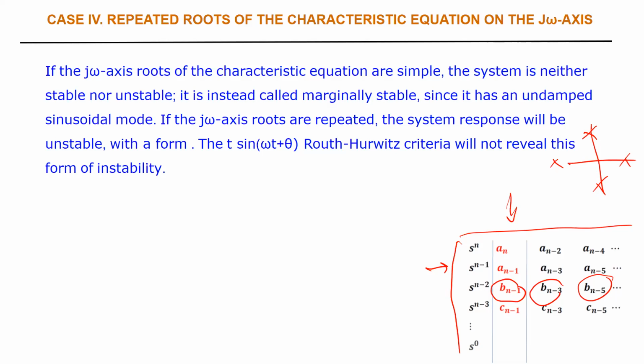The system is marginally stable because remember the definition of the input-output stability, bounded input, bounded output. With the pure oscillation, the output is bounded. So we call this type, which is between the stable and unstable system, the borderline. We said our system is marginally stable.